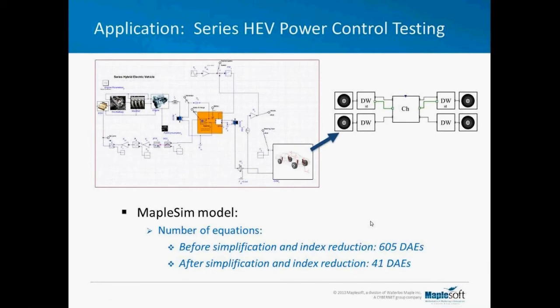And this is why we've developed some new tools for rapidly developing chassis models, similar to the sort of modeling framework you see within Adams Car. So here's a very simple schematic that Andrew's going to explain in a bit more detail shortly. So here's our vehicle chassis. Here are our 4 tires, 2 on each side, and the DW are blocks representing an entire double wishbone suspension. These are basically plug-and-play suspension components, and we could replace this with a McPherson or a trailing arm or a multi-link, and it's simply connecting the lines in order to change one suspension with another.